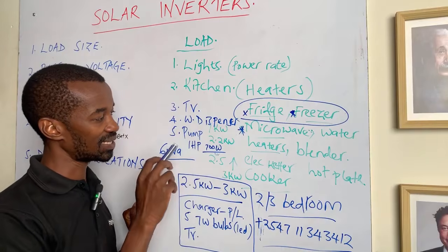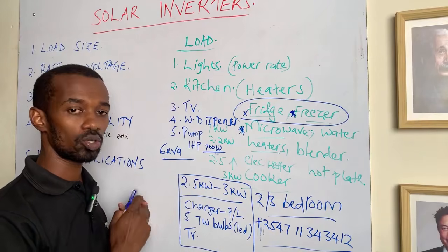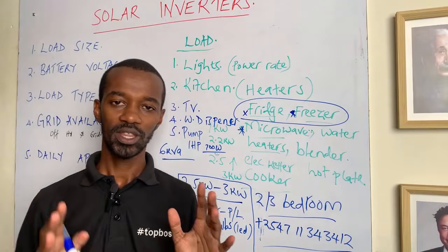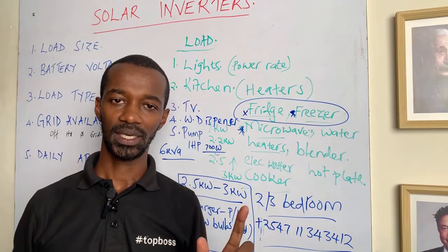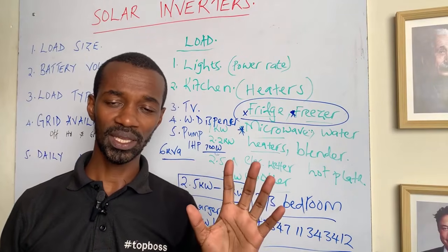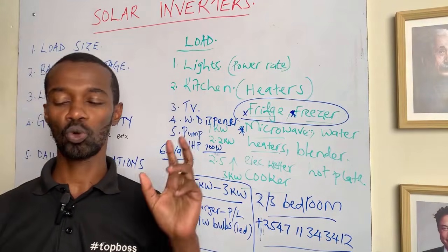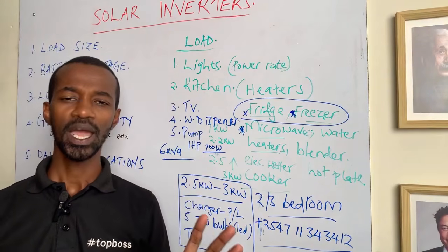All right. If it is an entirely off-grid system, you require more panels because the source of energy for that system is the panels. All right. Why am I now mentioning the battery at this point? Simply because the panels also will require to charge the battery.